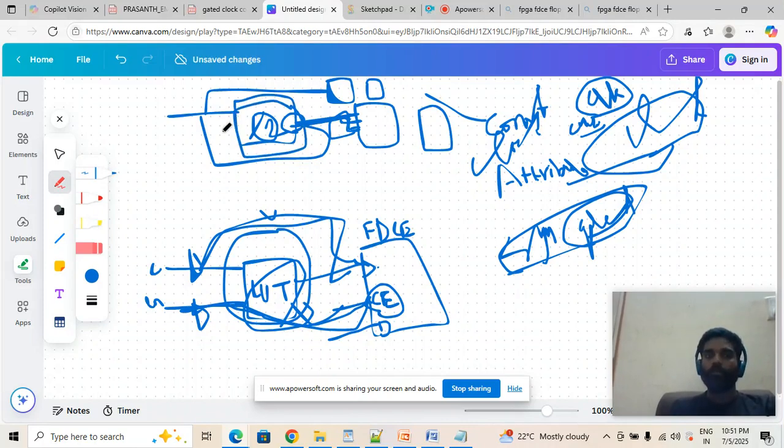It will use some LUT inside, or register inside, to implement the divide by two logic. Register inside, it will use it, and what happens? The tool assumes it's a clock enabled path. So in that case, we have to modify the constraint that we could not write at the beginning. We need to understand what is the alternative path the clock is coming from. With that we need to get this new clock name, and do this division operation. Once again, we change the constraint with respect to this new clock name and add the constraints, and then only the circuit will work as expected.